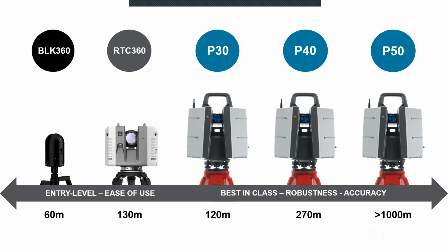And tomorrow you get a project in Hatta Dam or somewhere where you want to construct a dam or you want to have a bigger area surveillance. In that case, you can upgrade the same scanner to P50 and you can capture up to 1 kilometer range. This 1 kilometer range is basically a radial range. So in real terms, you will capture a 2 kilometer diameter.